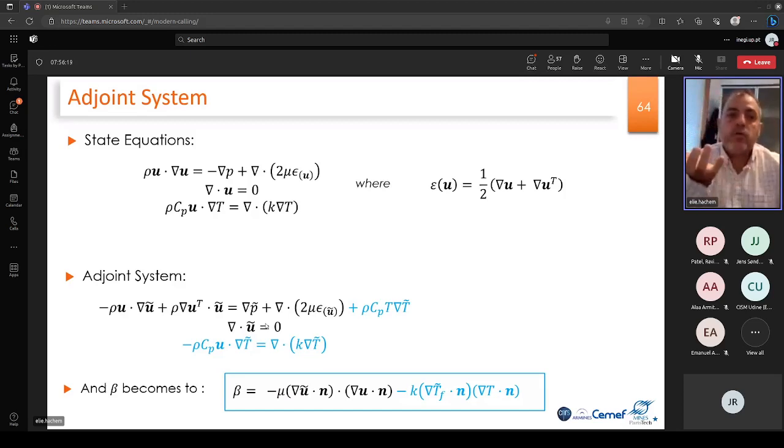So now I have again my whole system. By adding the temperature to it, I solve three equations, three adjoint equations. Maybe for you it's too much, and then I get a convective velocity. I use it to convect the interface, what we call the level set. If the interface moves from one location to another, maybe I can follow it with a mesh adaptation, and then evaluate my cost function. If it's not respected, evaluate also the surface constraint if I have the volume constraint, and then iterate in order to converge my system.